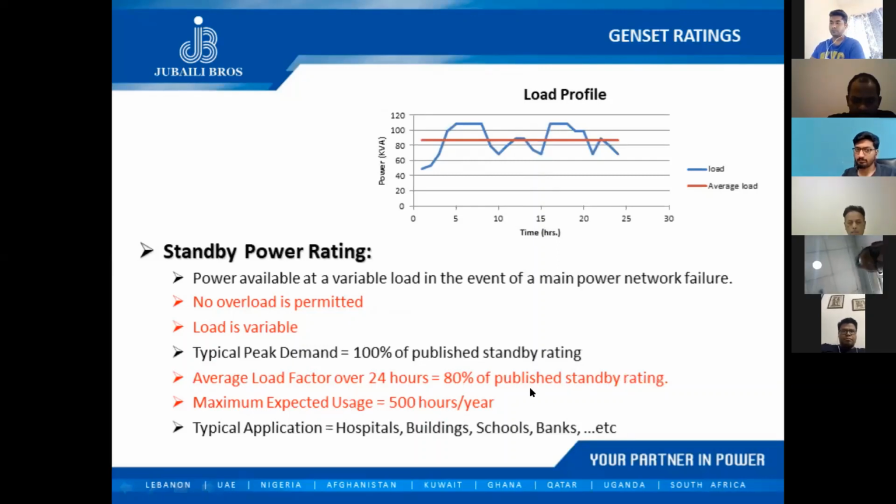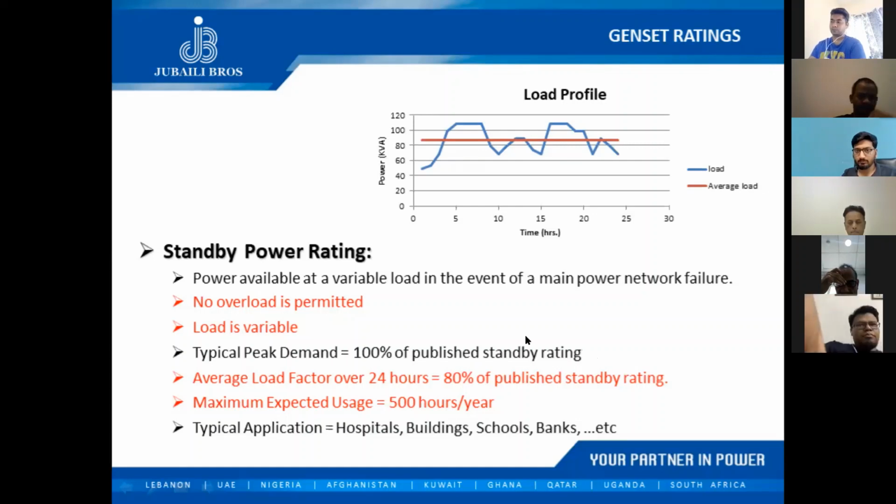Now, a very important point related to standby application. We said that the typical peak demand is 100% of the published standby rating, which is 110 kVA. Can we use this 110 kVA continuously? Can I use it for 3 hours, 4 hours, 5 hours, let's say?